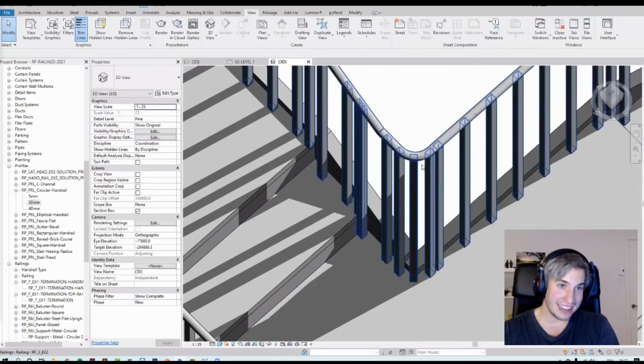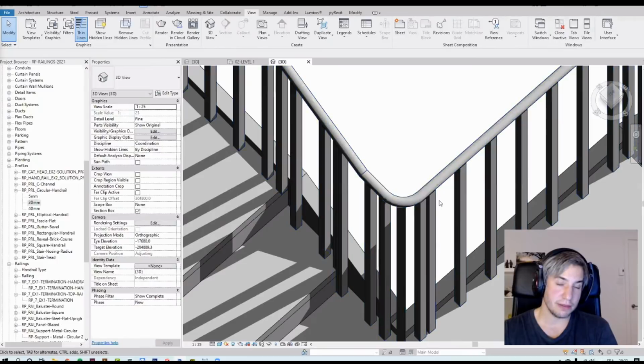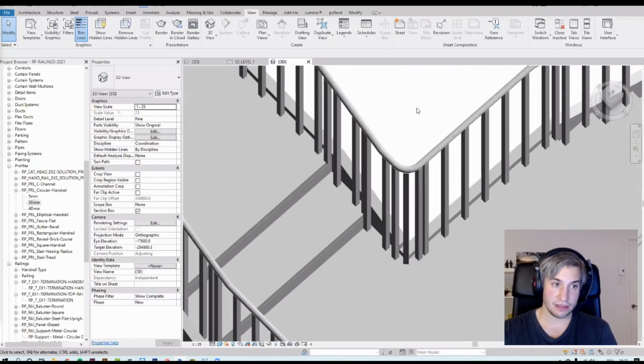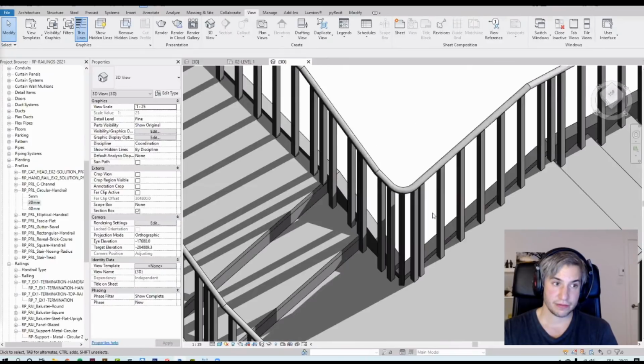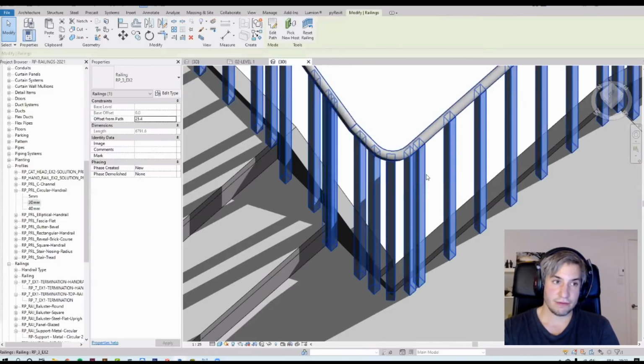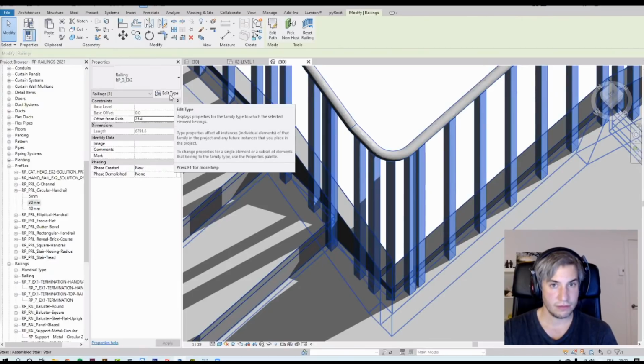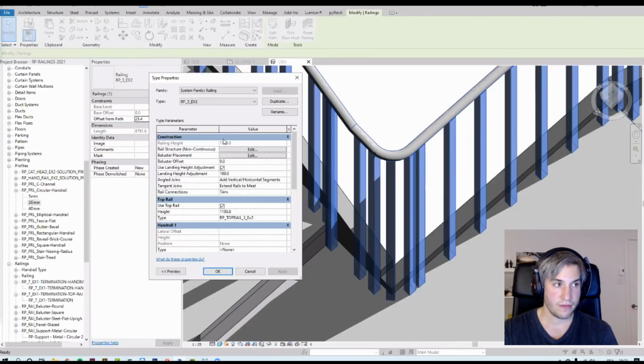Usually when you do that, balusters will work. So you could argue that if you're going to do something like that, it's better to do it in the path itself. You are still dealing with an issue now. You're creating an end to the path, right? So that's why you're getting those extra balusters there. Yes, that's right. You're creating two ends basically instead of one end. So you may run into that issue too. But it all depends on what you're doing, I guess, right?